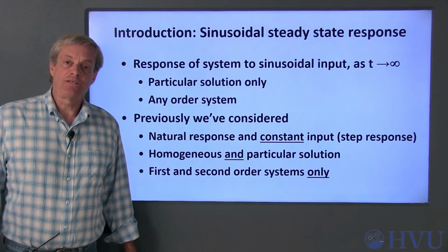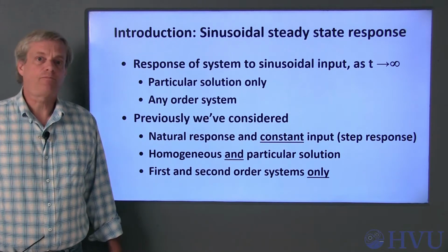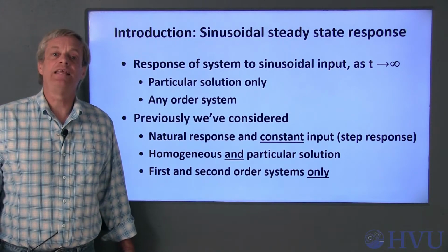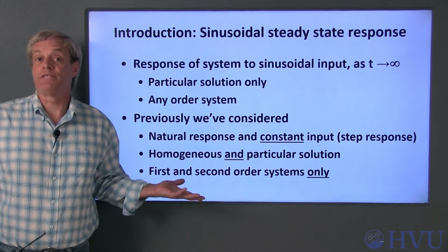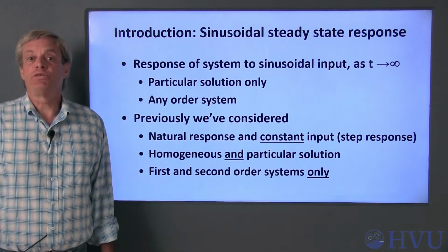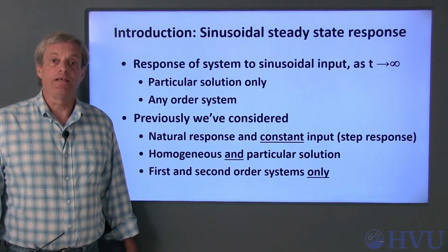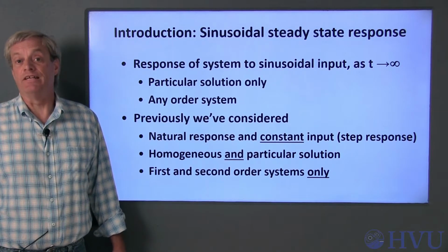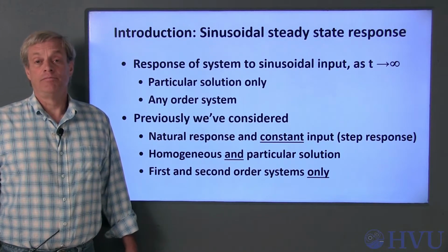We replace capacitors with open circuits and inductors with short circuits and solve the circuit. We can do that same process with any order circuit if the input is constant and we're only interested in a particular solution. In the case of a sinusoidal input, the particular solution is not a constant, so the solution approach is more complicated, but we still don't need to worry about the initial conditions and the associated homogeneous solution.